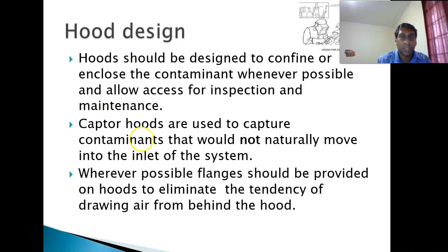So this is a very critical point for the exam. What do you consider in selecting a hood? For example, like an employer. So you must consider things like can they get access to it for maintenance, and how often would it need to be inspected after the initial installation. So those are points employers would normally want to consider before selecting an LEV system.